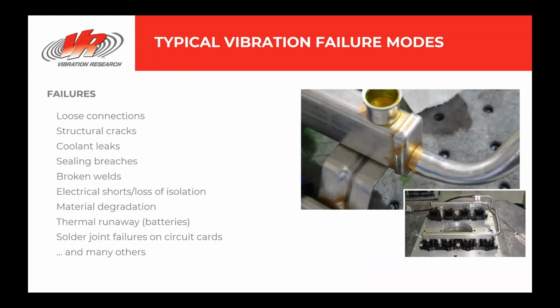When we think about battery vibration testing, there are several common failure modes found in battery packs. One of them, loose connections. Vibrations can cause the electrical connections between batteries to become loose, reducing the conductivity of the pack. You have mechanical damage, in which vibrations can lead to the mechanical failure of the battery pack, causing the outer casing to crack or deform, which could potentially result in internal damage, including seal breaches and leaks of coolant lines and so forth.